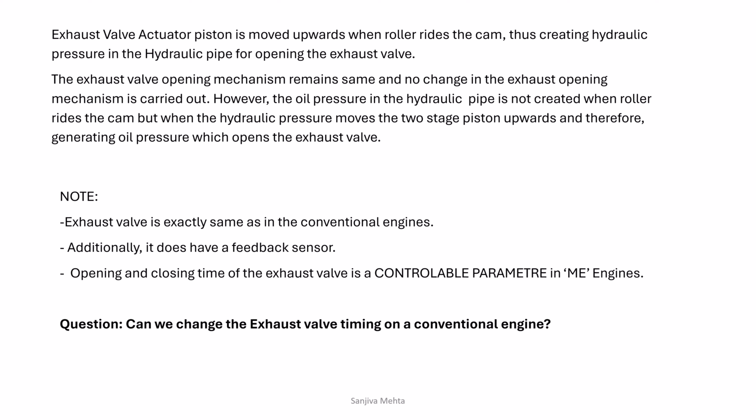So, what is the effect of early closing and late closing? I have been asking this question earlier also. Now I give you the answer, if you were not able to find it. I am sure you must have found the answer. If the exhaust valve is closed early, the compression pressure will rise. If the exhaust valve is closed late, the compression pressure will drop down, will be lower. This phenomenon is utilized later on when we are doing the performance. I will tell you. So it's a very useful phenomenon.